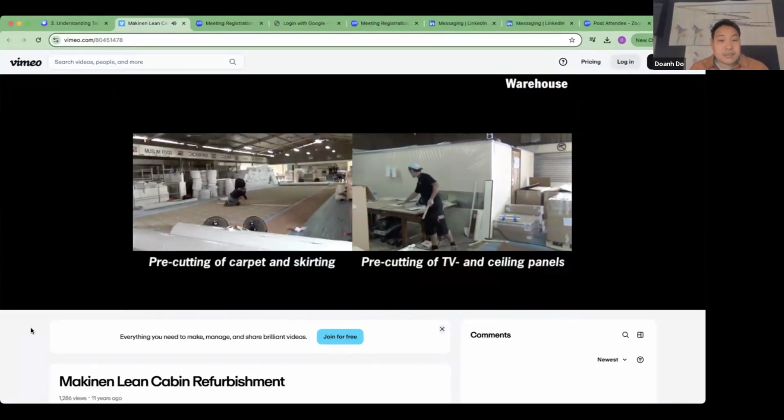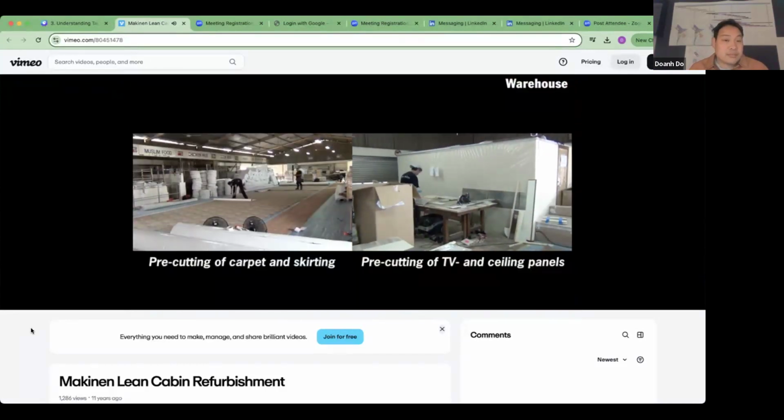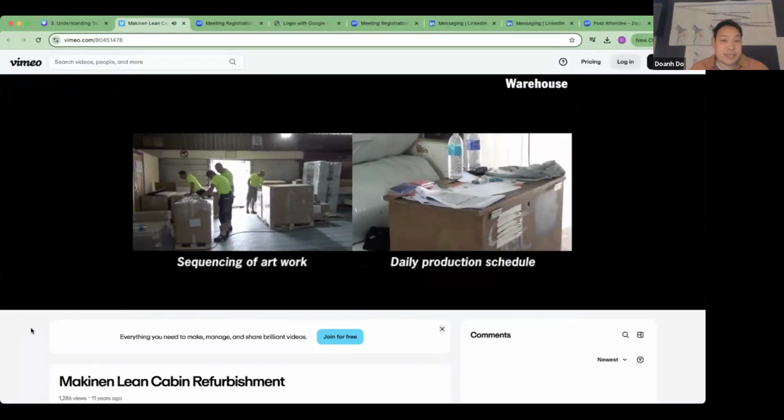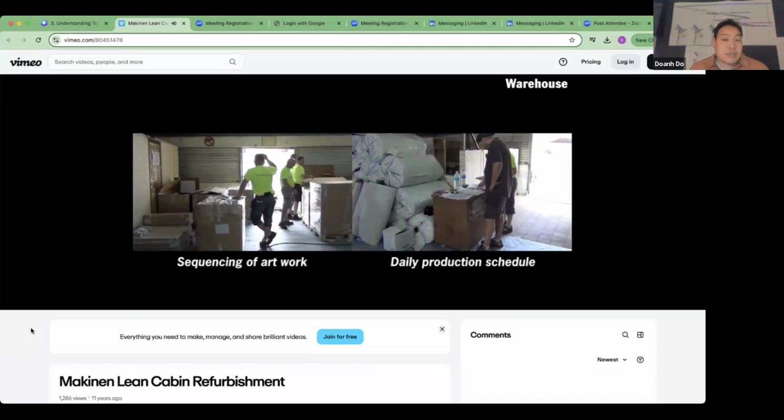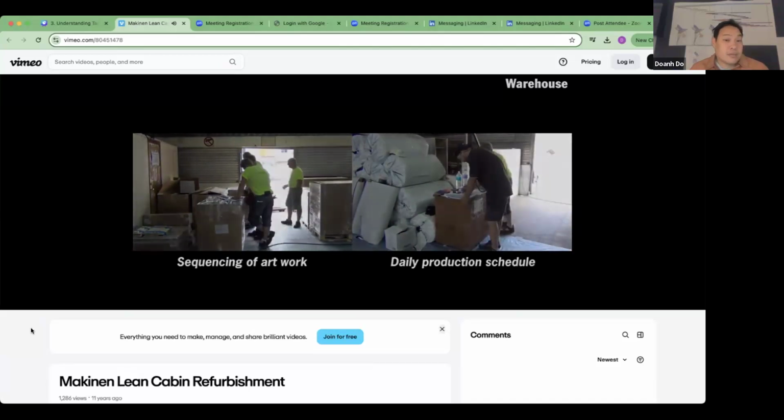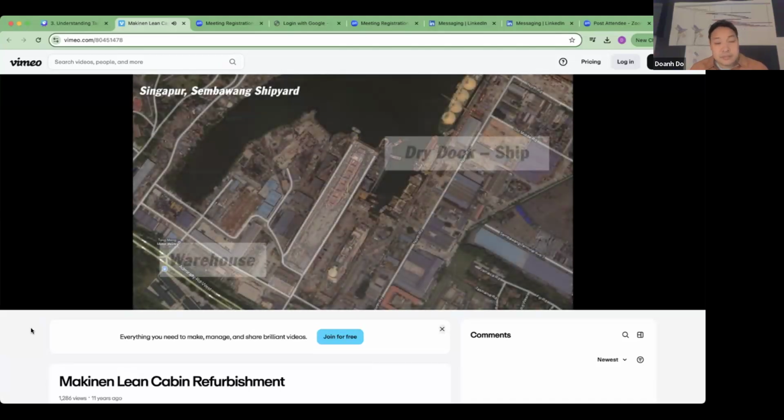Okay, so because you're trying to keep the 20 minutes or so TAKT time, a lot of things have to be prepared, prefabricated ahead of time. And you gotta also create a very clear production schedule for the day, because if you're off, it's gonna waste a lot of time and money.